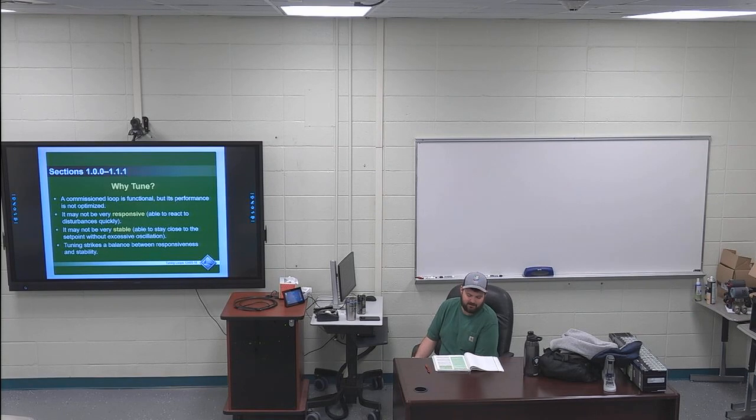The time constant up in the top right, I have highlighted as an online test question. It's a measurement of time that describes the response behavior of a particular control system. A single time constant is the time required for a controlled variable to change by 63.2% of the amount that it must be changed to reach steady state.